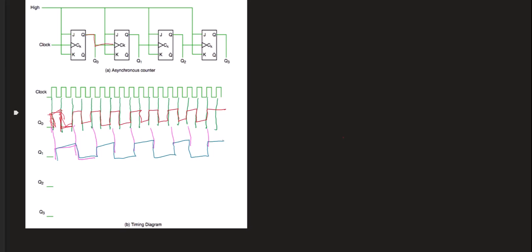Okay, and now y'all see if you can fill in the signals for Q2 and Q3 on your own, and I'll do it up here as well, and then you can check yours after you have done it. Always pay attention. They could throw one at you where perhaps it's not exactly the same on each one, but it is on this one. It's always the output from the previous flip-flop is the input into the next one.